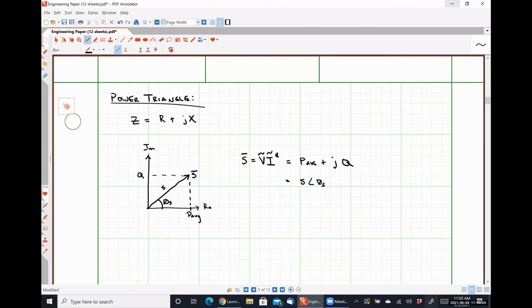All right, so as I said before, this simple graphical tool contains all of the information provided by the numerous mathematical relationships that we developed previously. Additionally, further information about the behavior of the load can be inferred by looking at the power factor angle theta S. So if theta S is equal to 0 degrees, then our power factor is exactly equal to 1, and we know that the load is purely resistive, which means R is greater than 0 and X, its reactance, is equal to 0.